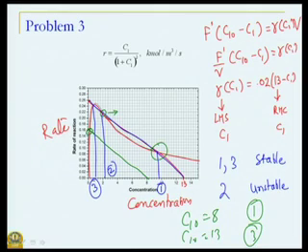That point would be where this operating line with a slope is just tangent, that is, that straight line is tangent to our reaction rate curve, that will be one limit. But that tangent can be found at two different locations. So, another tangent over here.